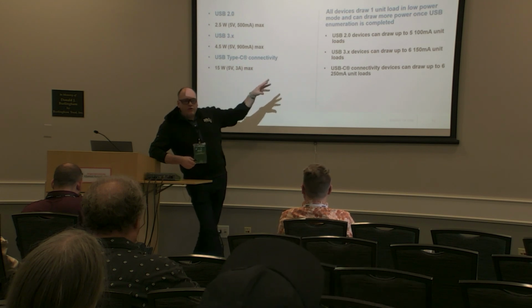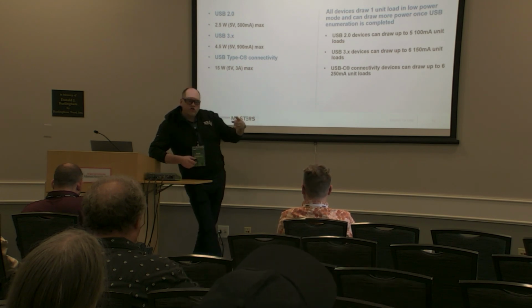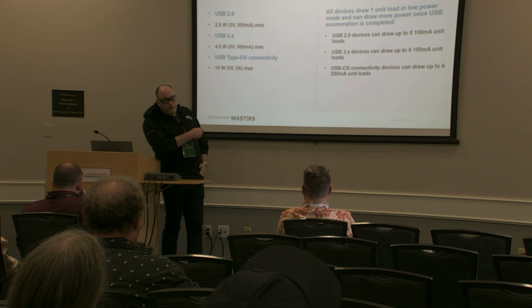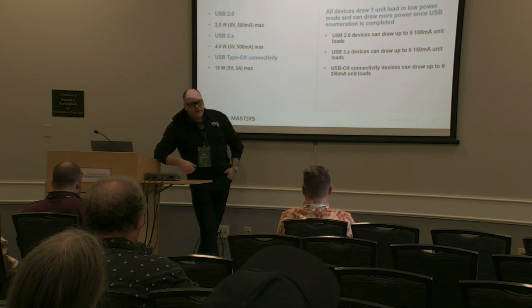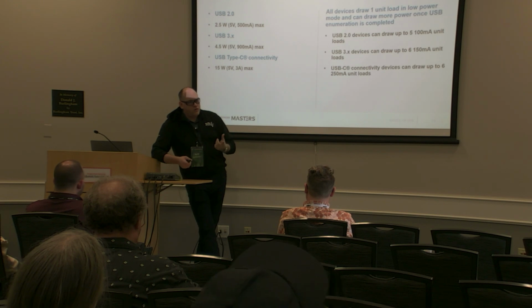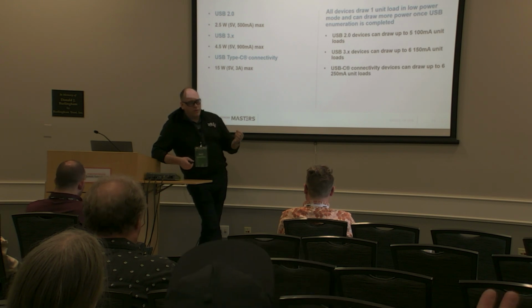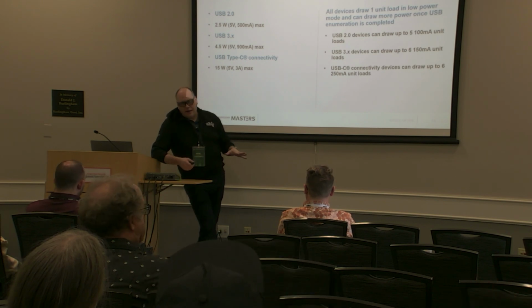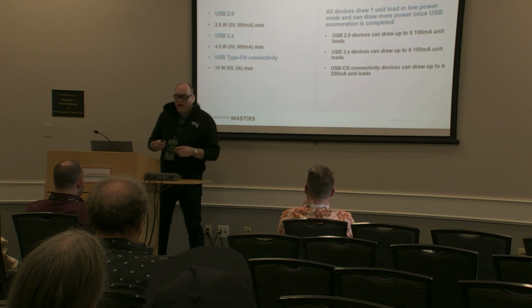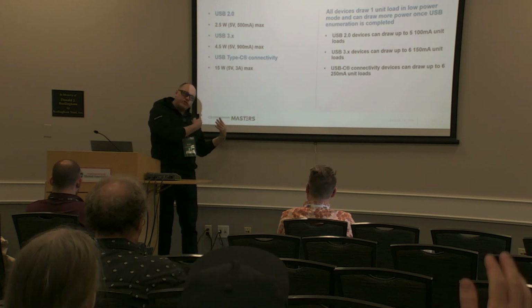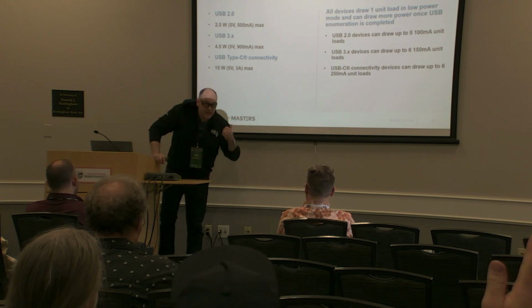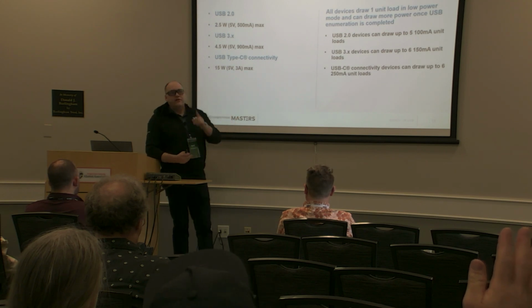But yes, you've only got what's available. So when you plug in the host controller, then all you're doing is bringing it back up to 900. That's all it's going to give you. Even if you plug 3 of those into the host, and then you try and plug a 4th one into the hub, the same thing's going to happen, right? But you will get all 3 plus whatever 3 are on the original hub, because they've got all the power that they need back on the original host.